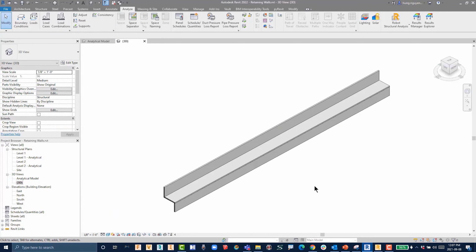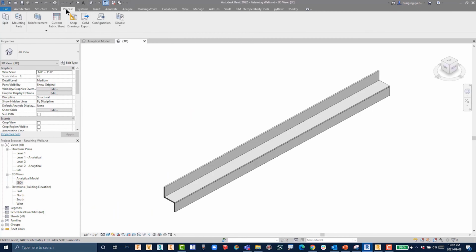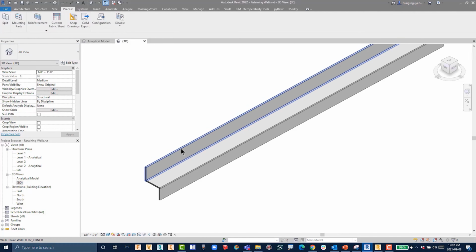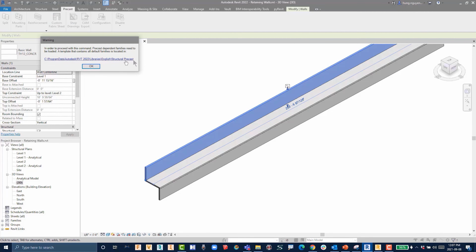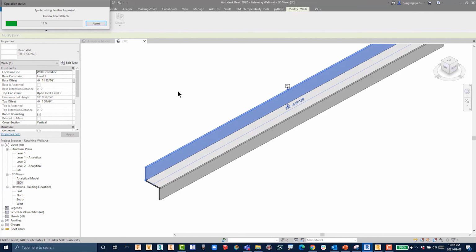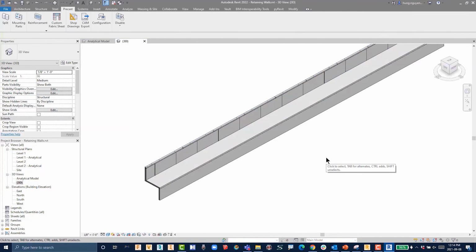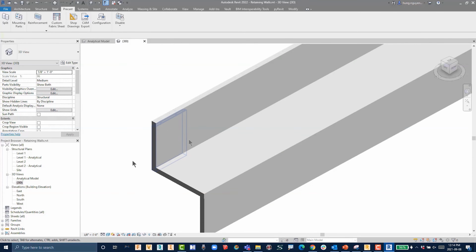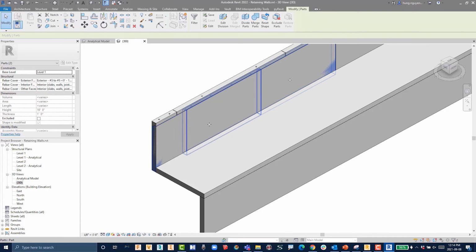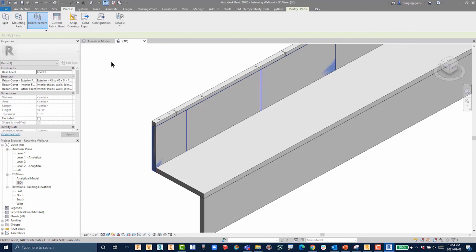So now switch back to Revit. Assume that based on that report, I would like to manually put the support that is the precast concrete. I can use the module in the add-on in Revit called Precast to calculate and subdivide the wall into panels. After the calculation is done, you can just simply select one of the parts that the add-on divided for you, and go back to the Precast and build the reinforcement for that.